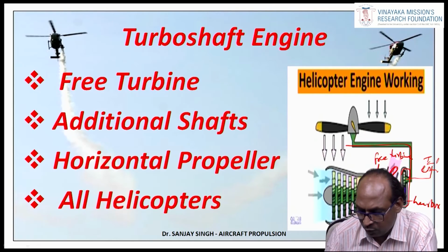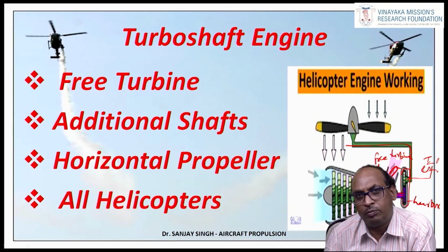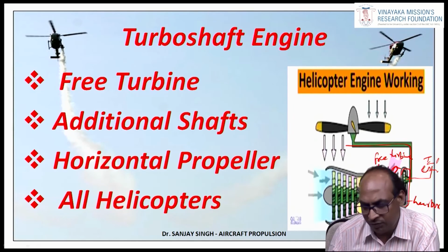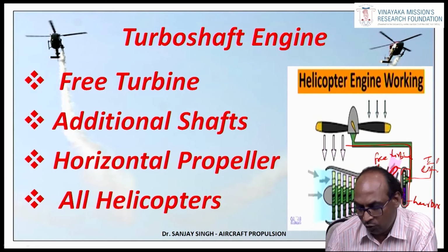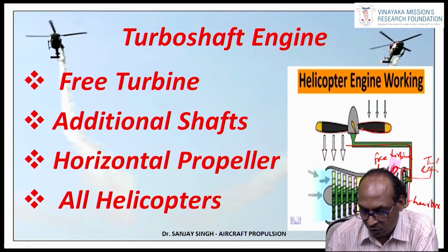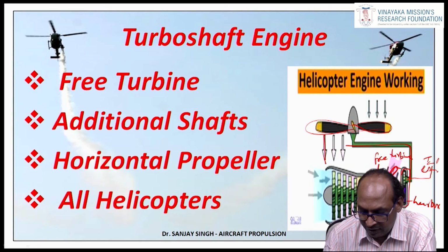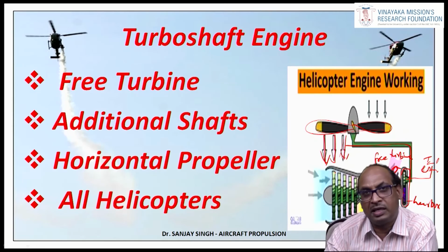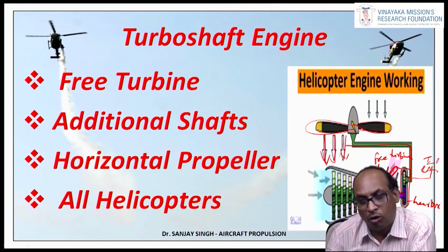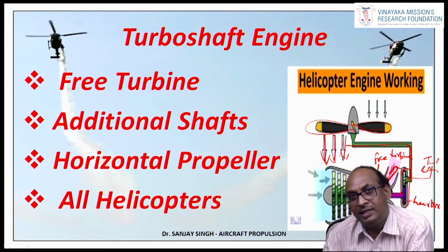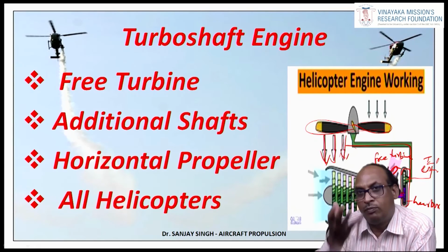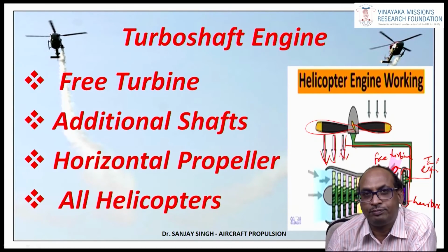But this thrust produced by the gases moving out from the nozzle is very, very less. The thrust is being produced by using this main rotor. So in this main rotor, what is there? This main rotor will make the air move downward at higher velocity towards the ground, and thereby the ground will exert a force on the rotor blades, which is attached to the main engine, and the main engine is attached to the helicopter body, thereby the full helicopter body will get lifted up.